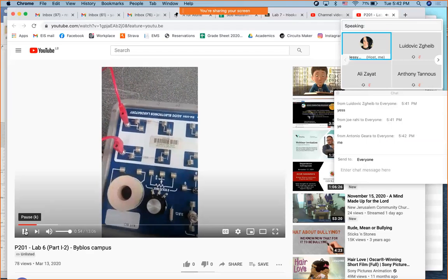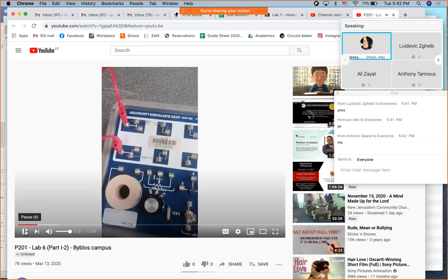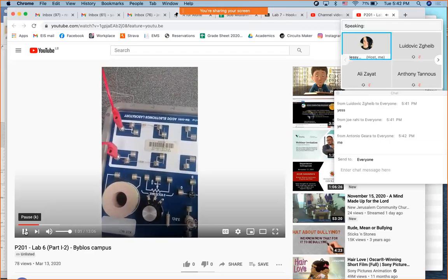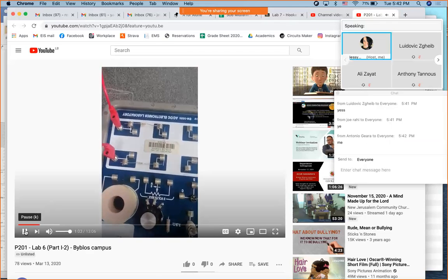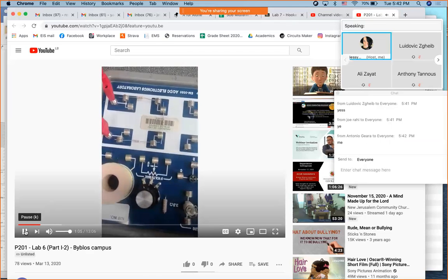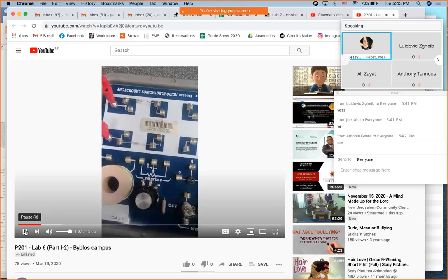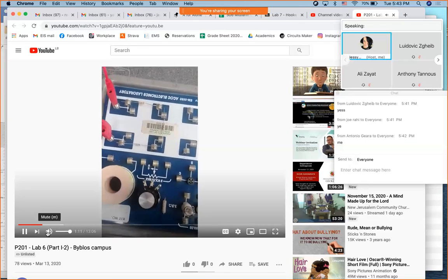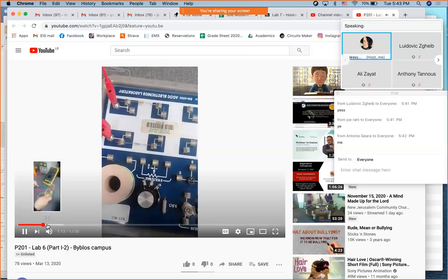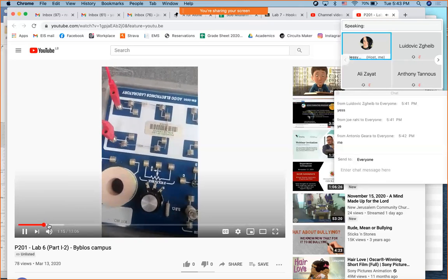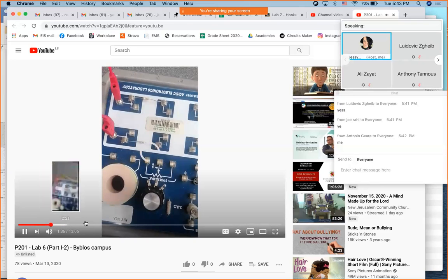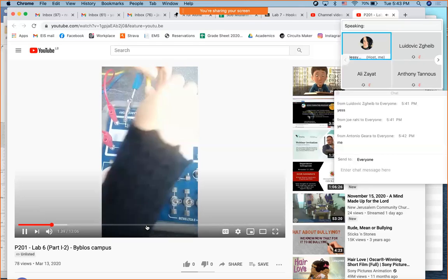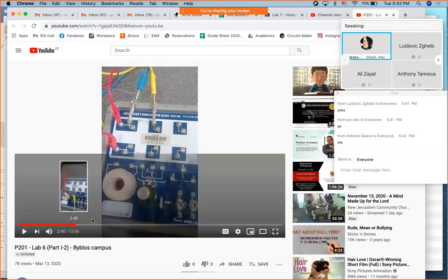We fix our voltage at 5 volts. This will be V total. Now we will measure V1, V2, and V3, and V equivalent of R1, R2, and R3. This is a series circuit. So V1 plus V2 plus V3 should... All right, let me see. She's gonna show you how to do the connections, and they're really easy and interesting to do.